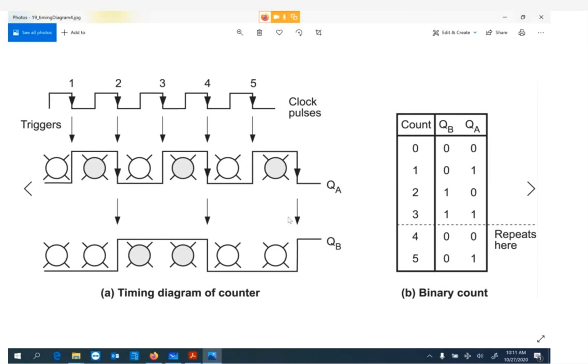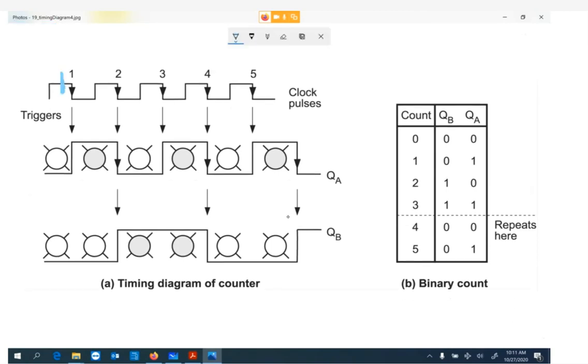So there's your trigger, our trailing edge trigger, right? So that will trigger our 1 count. The next pulse, the trailing edge, turns this one off, triggers our 2 count. Now you got to think of this as our 1's column and our 2's column. And then of course with both of them on, that's our 3 count, and they indicate that here.